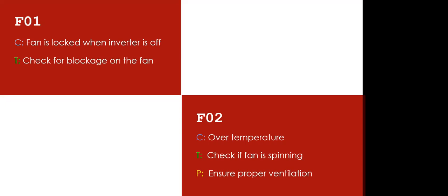But if you do all that, we restart, we check the fan, nothing blocks it, and there is no physical thing that we can say, okay, this is the issue that caused the fan not to roll, or it's spinning, but it's still showing F01. So we count that one as a fault, which will require retrieving to the service center.